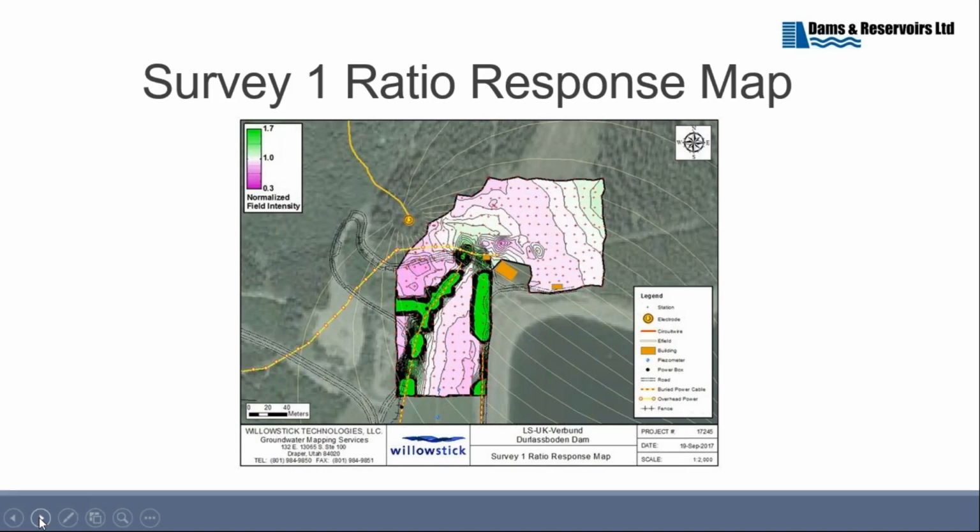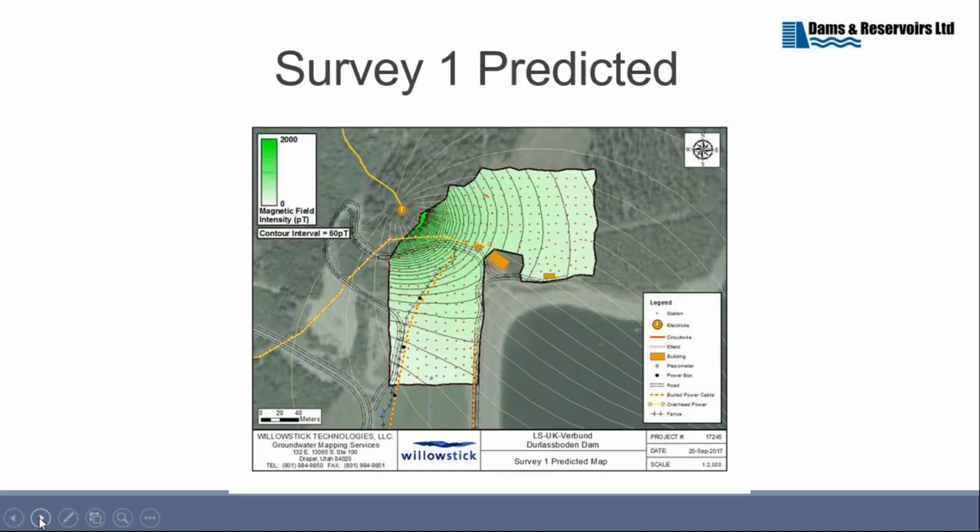And you can see down in the toe of the dam, the base of the dam there, the various blue points where water was arising before it met the road downstream and all the piezometers. So the whole of the valley downstream of the toe of the dam down to the main road had been infilled and various relief wells put into that. So the owners were getting to a stage where they had nowhere to go. They had to really try and solve the problem once and for all.